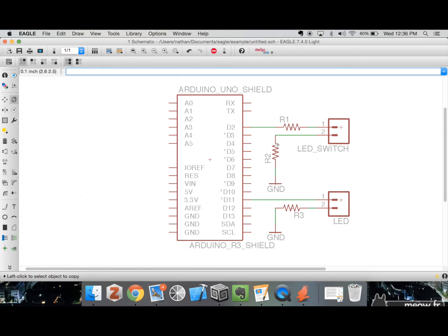So we're going to go in and we're going to delete the components that were placed by accident. Now in Eagle, you don't really want to move things and try to pick up the trace and then reattach it. It's going to run into issues and things not actually being connected. So if you do make a mistake like we did here, then you're going to want to just delete the mistake and then replace it again. So I'm going to type in DEL, and that's going to bring up our delete tool. You can also click on the trash can if you're so inclined. And then I'm going to delete this resistor, this line, and this ground.